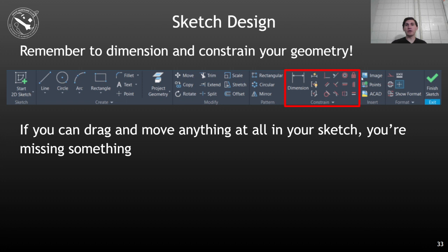And then these little things on the side right here, the rest of these are different constraints. For example, you can have collinear constraints like this one right here. You can have perpendicular constraints, locking things to be either horizontal or vertical, or there's this lock button right here. You've got tangent constraints, all of these different types of things. If you want to lock some geometry in place, but you can't really put a number to it, you can put a constraint to it. So basically you want to use any of these when you can't put a number to it. And if for some reason none of these work, this lock button right here just locks everything exactly in place. But if you are trying to design something and you're constraining something with just the lock tool, you're probably doing something wrong. So try to see if you can modify your design.